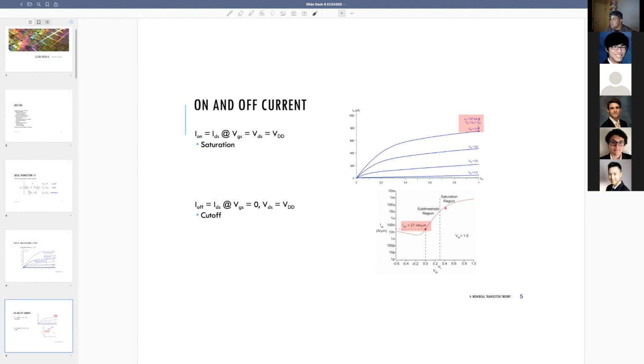Okay, so this curve is for a particular drain-source voltage. Remember, when we plot V gate-source versus the current, we have to keep the drain-source voltage constant. And when we plot drain-source voltage versus I sub D, we have to keep the gate-source voltage constant, because it's a two-dimensional plot. Anyway, our model would say that as soon as you get to the threshold, V sub t, this current would go straight to zero. But what happens is that once you're below threshold, it goes down, down. And notice it's going down pretty fast, because the current axis is in the log scale.